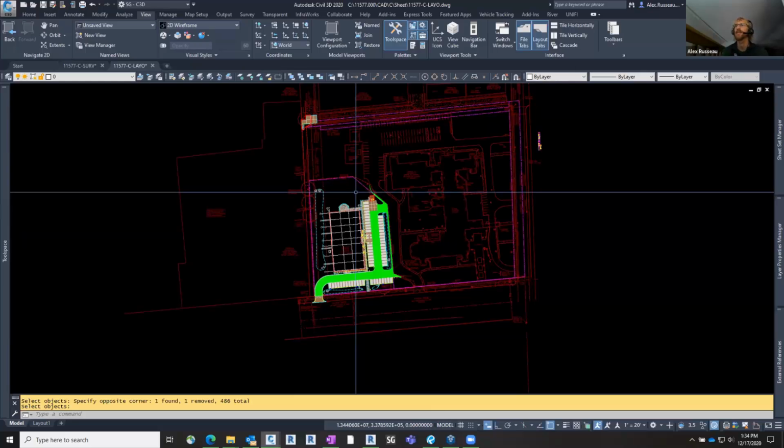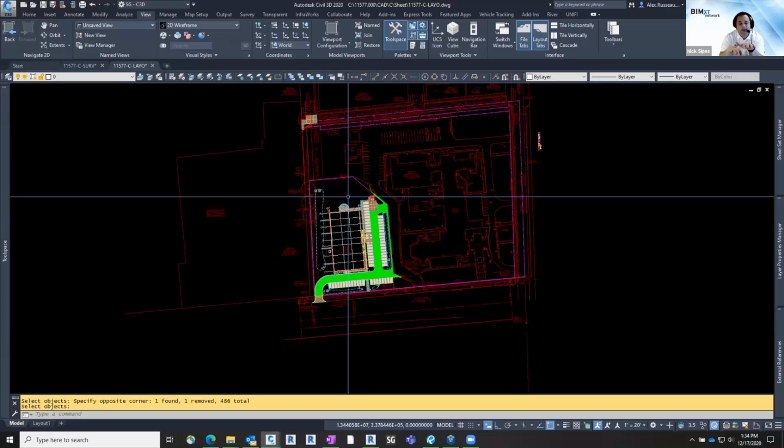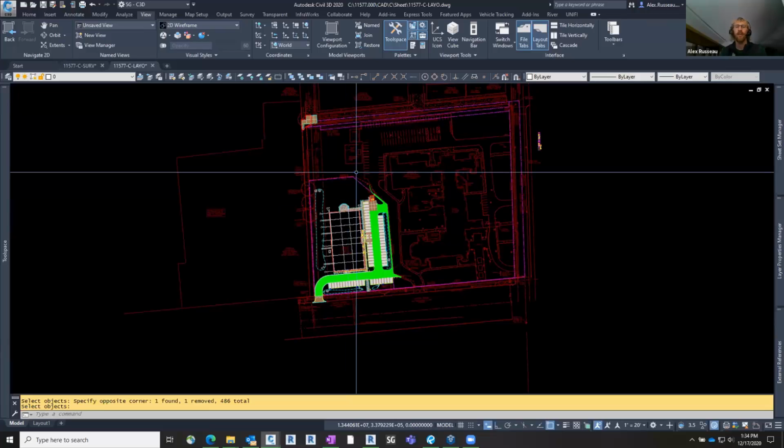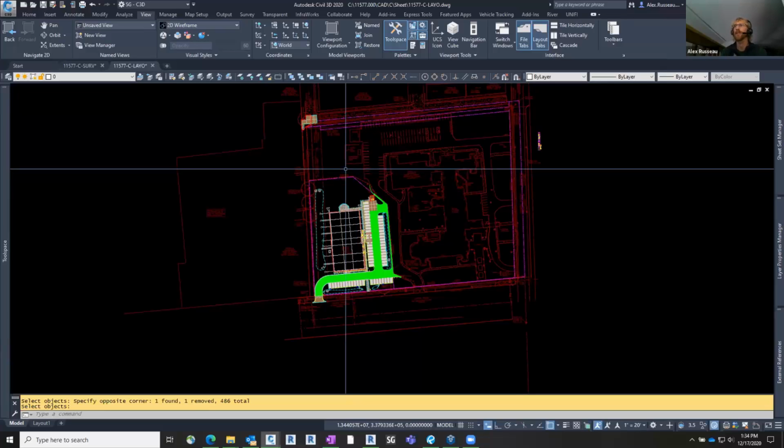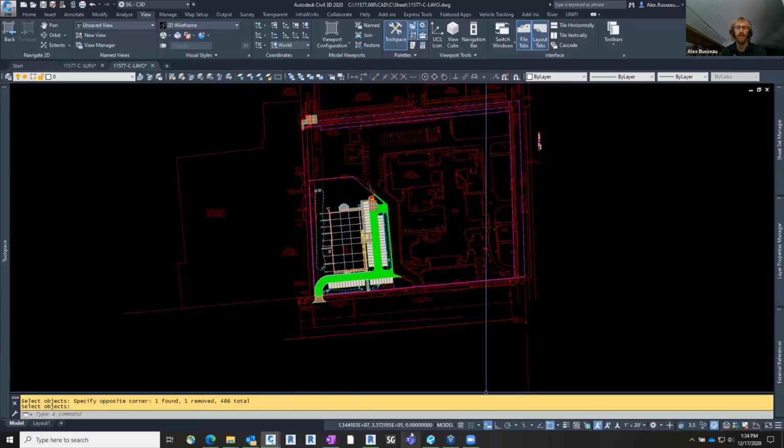I'm going to interject here because it's one thing that I've really liked about how you disassociate the 3D topography from the Civil 3D link. That way you can control those separately. The line work is one thing, and that's at the flat level, and then the 3D is a separate link, so you can turn things on and off. Yeah, and we've gone as far in our world as creating 2 files. We've had one that's just line work, and one that's surface elements. That does give you a little bit more control, and I think that might have been what Nick was talking about too.